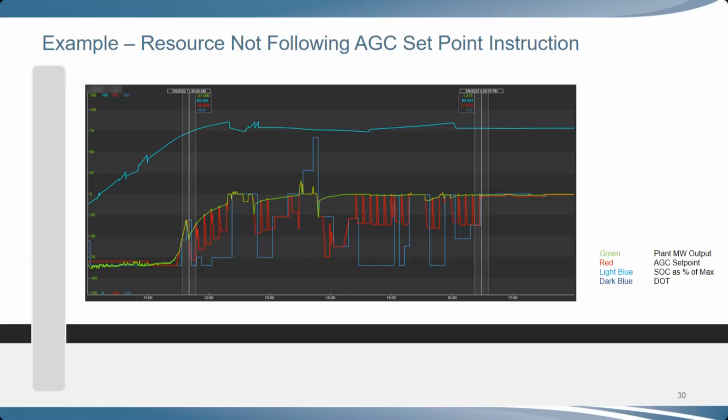Yeah, I can take this question, Heidi. So Kathleen, that's a great question. It is very in-depth. So you're talking two different scenarios. DOT is basically you're getting a 5-minute dispatch based on the 5-minute market, correct? So AGC, you're talking now, AGC set points are provided by the 15-minute regulation that you bid in.